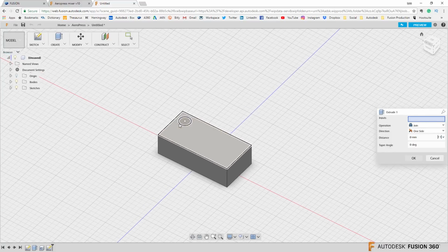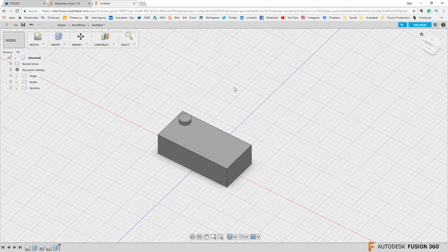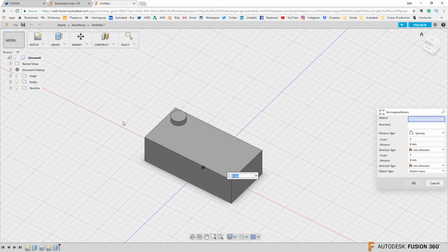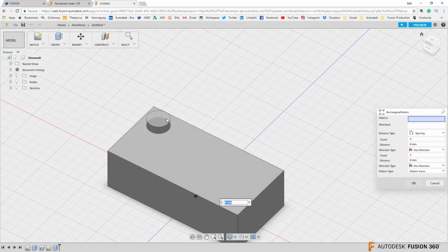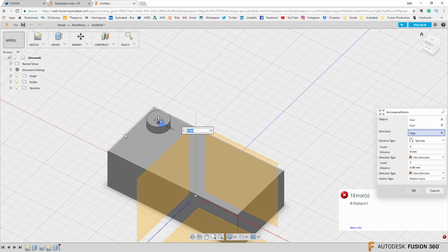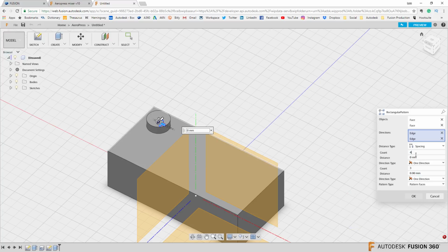Let me just, now I gotta finish this one up at 2 minutes. So we hit the half an hour, 1.8, there is that top. We got the patterning in here. Again, select the faces. Let's do some directions. We're gonna go in this direction. We're gonna go in this direction. Let's do 4 of these.